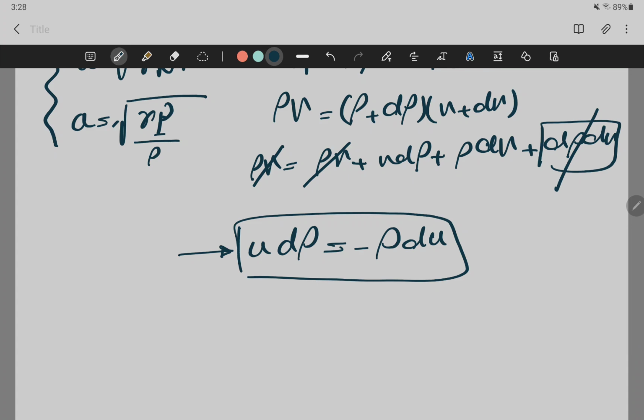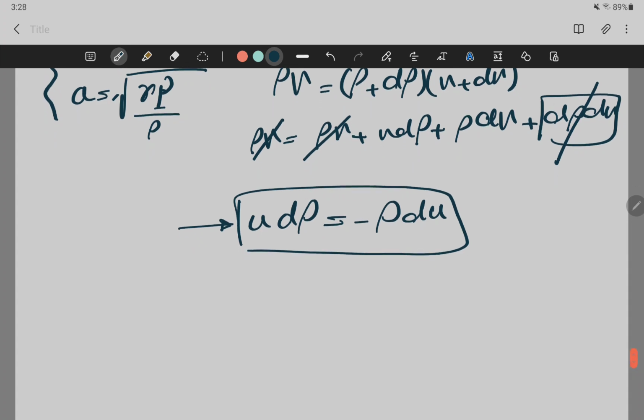What about the momentum equation? What can we get from the momentum equation? Force balance, or F net. What are the forces here? It is actually a very important thing that you can understand what is the force that is present here. The forces of compression. What do you mean by that? How can I find the forces of compression? Pressure times area. We call those pressure forces, right?